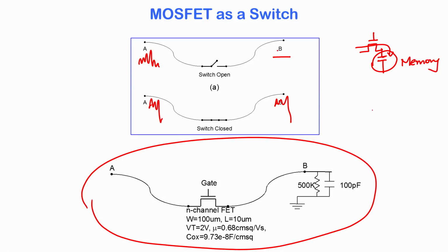The other applications are circuits and displays or any active matrix systems, wherein you have a MOSFET and a capacitor again, and you store charge, and then you have a light emitting material. So, for example, say an LCD: you store information on this capacitor, you open this MOSFET, and you have the voltage here driving the LCD, so that you can see the color, the different levels of brightness on your display screen.